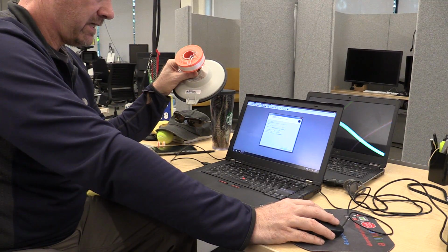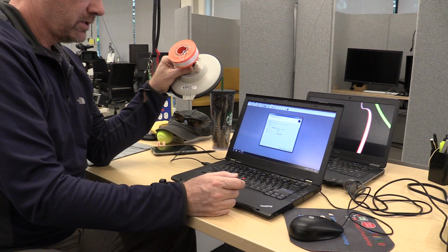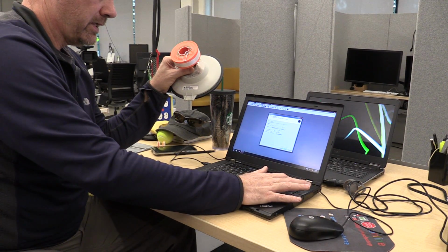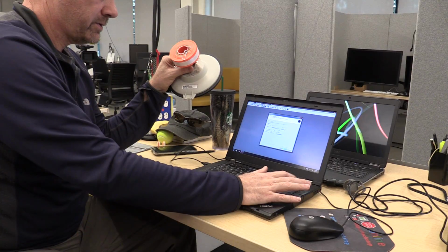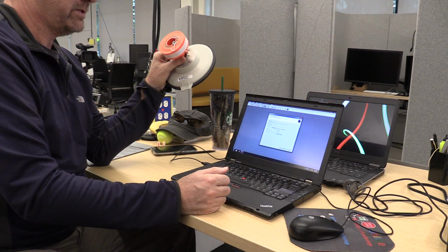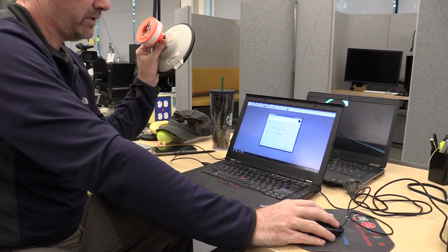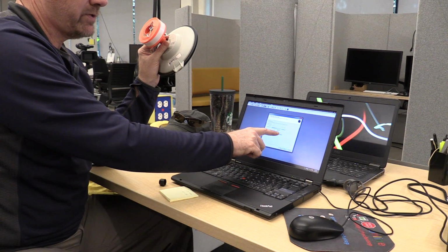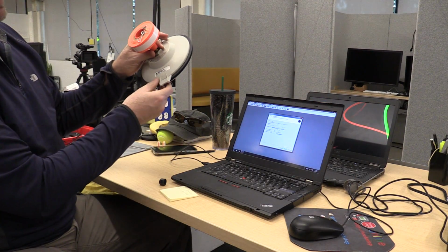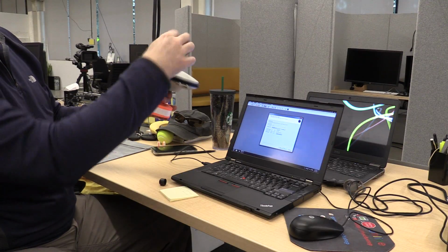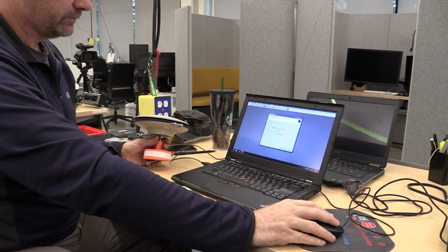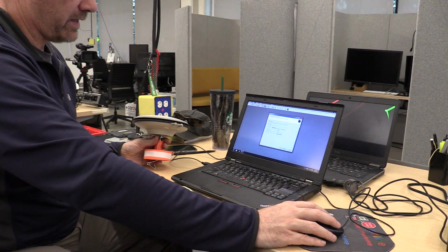And then as far as the height measurement goes, it's in meters. I know it's 72, so it's 0.072 meters. If I know my metric system, that's how many meters 72 millimeters is. And it asked, did I measure it to the reference plane or to the phase center of the antenna? The phase center of the antenna is somewhere buried inside here. So I'm just going to say I measured it to the reference plane. And then I'm done.